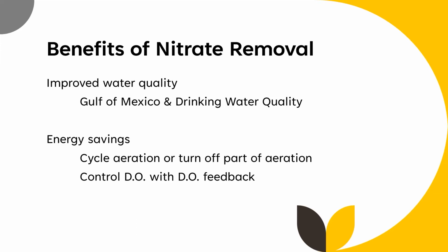As plants get comfortable with nutrient optimization, to have good, reliable nutrient optimization, they will need to control their dissolved oxygen with a DO feedback to control the speed of their blowers or their rotors that are supplying air to their system.